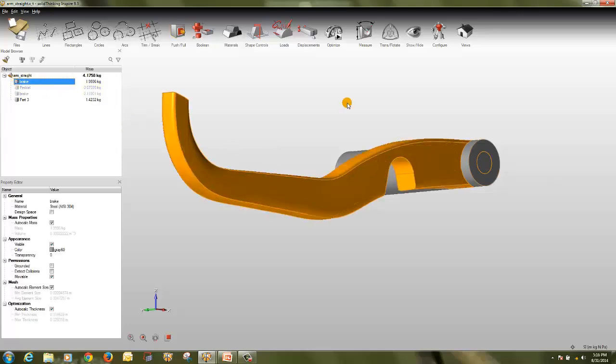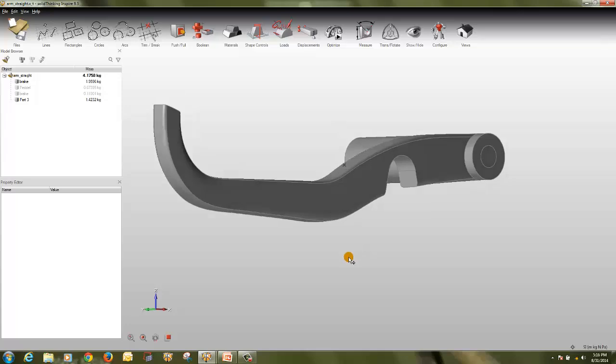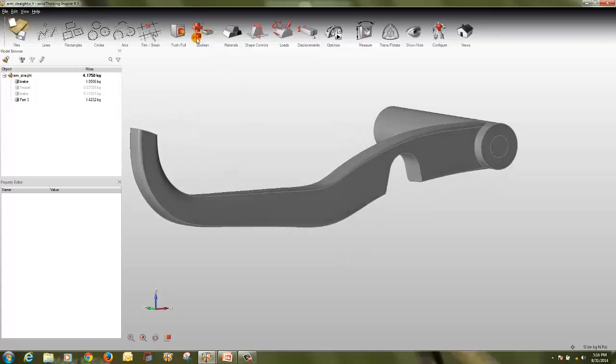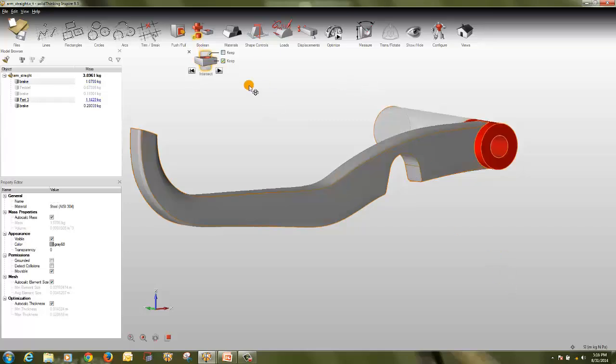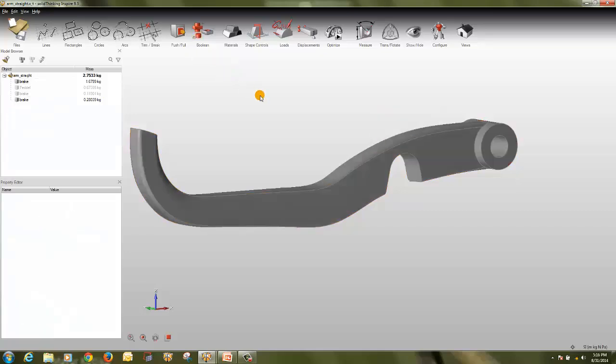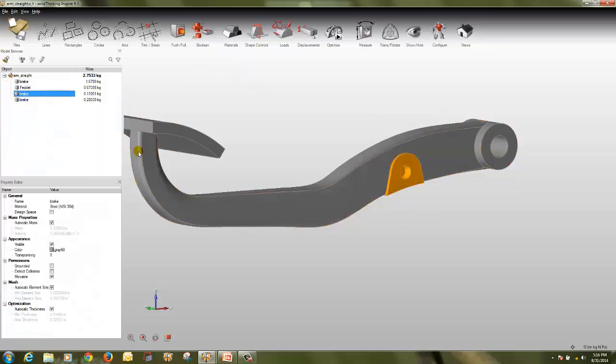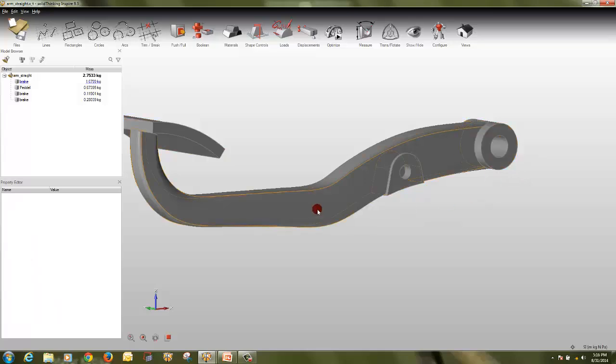turn on the other component, same intersection option, select this part and click on perform the operation. So now I will turn these on. So now I have these three as different components. So these three will be a different component which I can take as the non-design component.